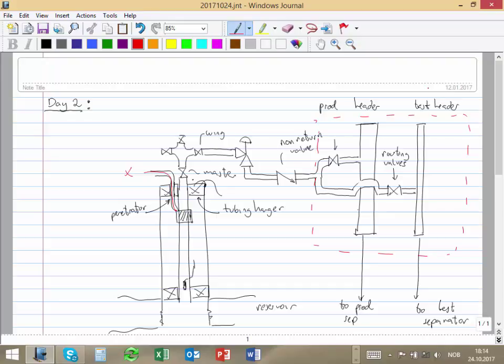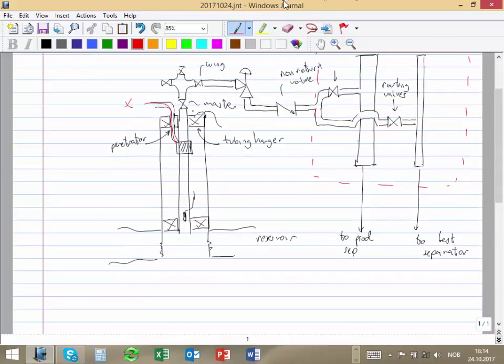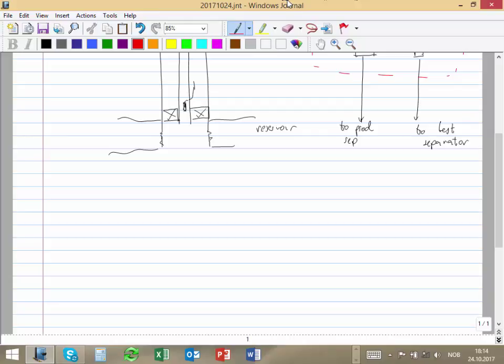So you also have to make another sacrifice for subsea systems. You have to make the lines the same size. Okay? And again, extremely expensive. But we have to. Otherwise, wax will start to accumulate on the wall, and then the system is plugged. Let me know if you need more time to write. Okay, so that was the conclusion.